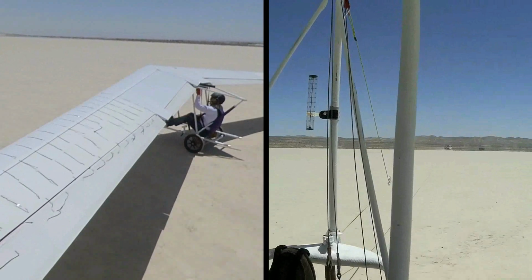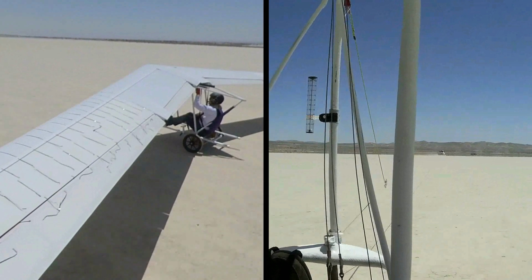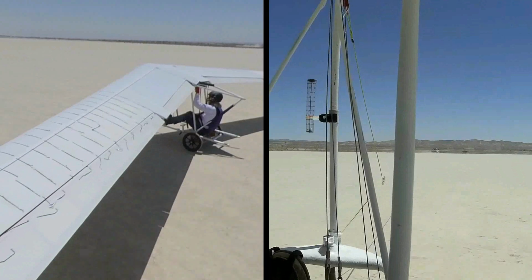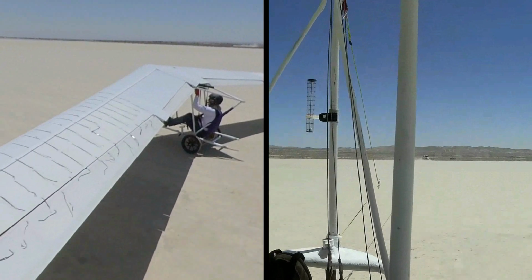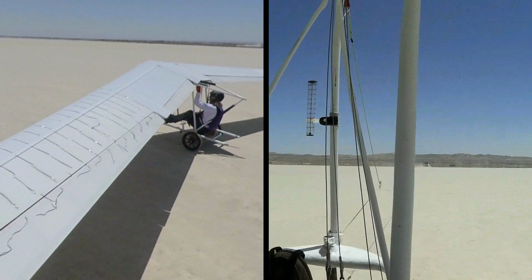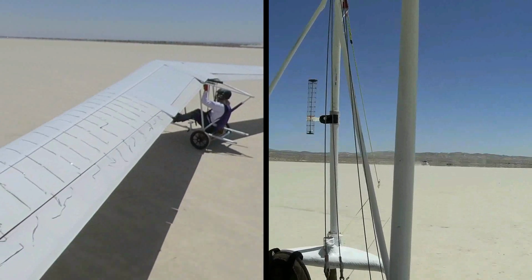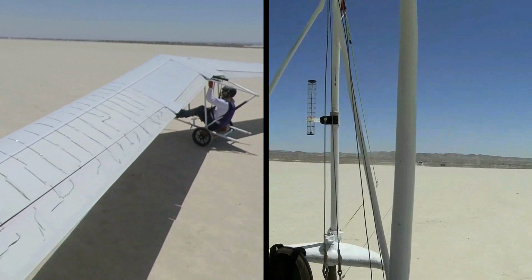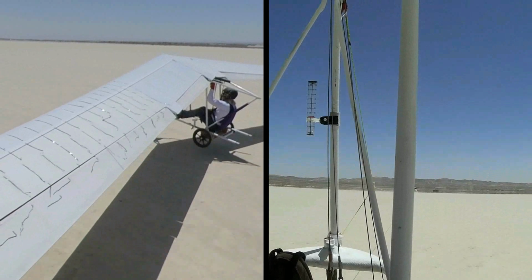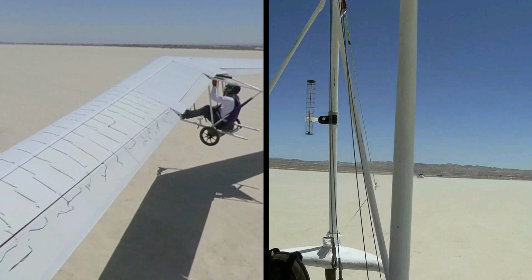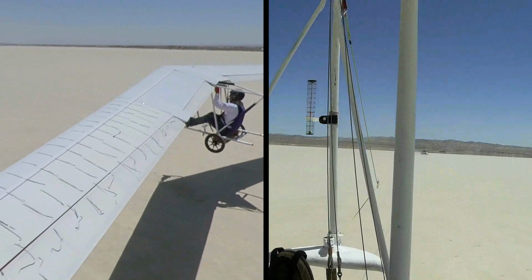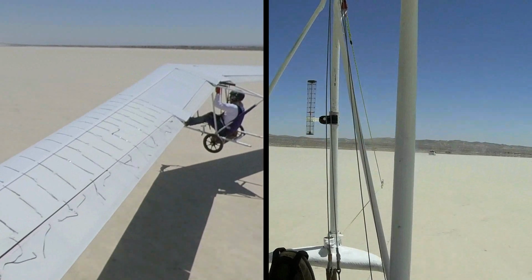So I think we're up to about rotation speed here. We're up about 15 plus. Stall speed's 23 miles an hour. And I think you're going to see me rotate here shortly. As I rotate, the elevon comes back up and the flow starts to improve a little bit over the elevon, and I lift off. But then, because of the nose-up pitching moment from the Y bridle, I have to put in more down elevator. Then the flow separates even more, goes out along the tip.